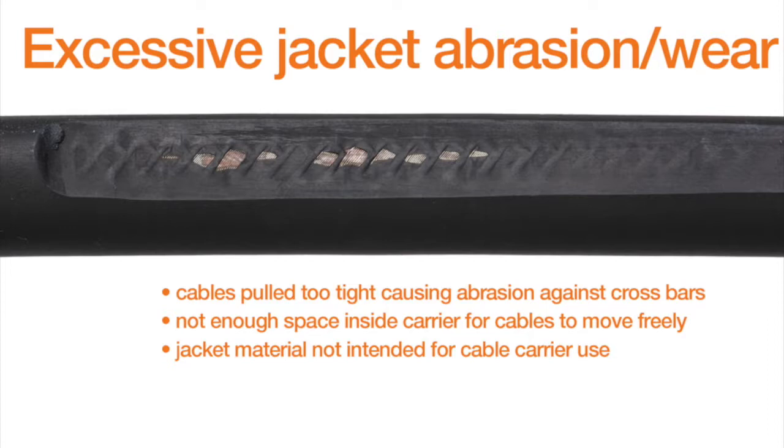So if they're up against other electric cables or hydraulic hoses or pneumatic hoses, any other kind of media running inside the cable carrier, if you pack a cable carrier too tightly and you fill it with too much media, they can have abrasion and wear just by rubbing up against the other things next to it. And the third reason for jacket abrasion is that the jacket material is not intended for continuous flexing inside of a cable carrier.